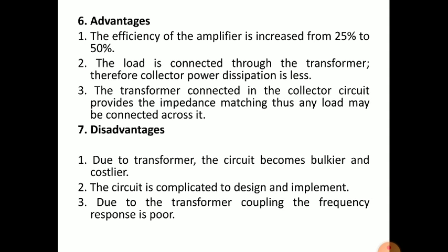The transformer connected in the collector circuit provides the impedance matching. Thus, any load may be connected across it. So, impedance matching will happen. So, any load if we can connect, according to that, the adjustment will happen. We need to select the proper turns ratio.